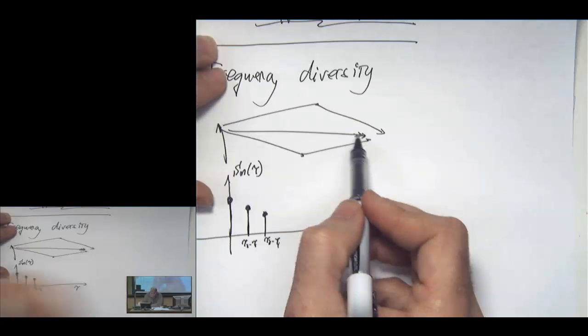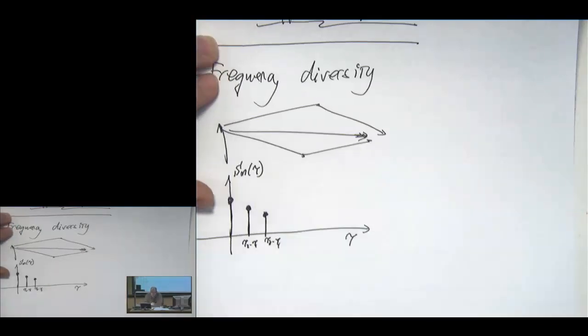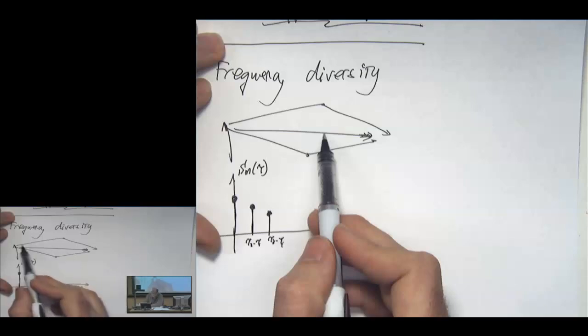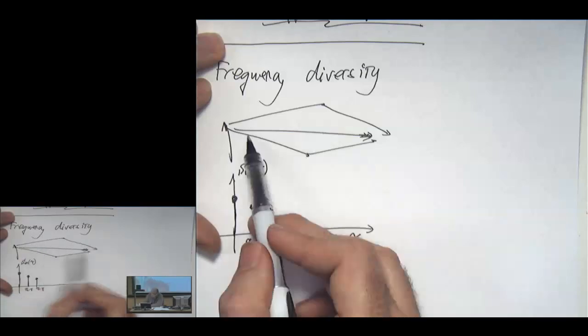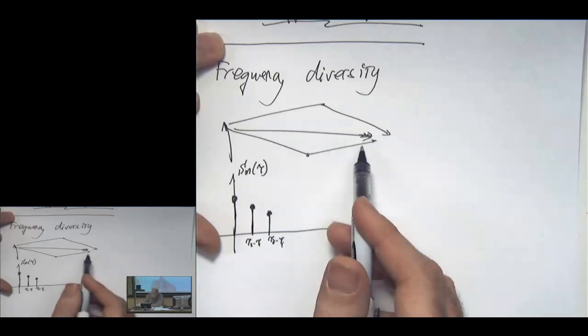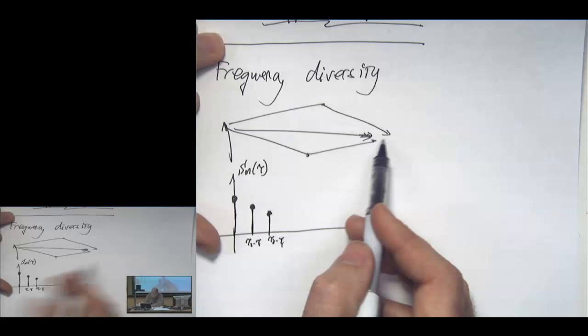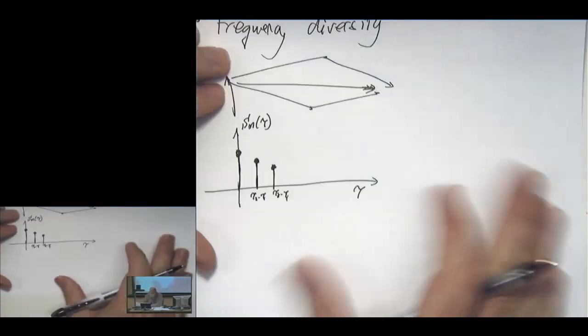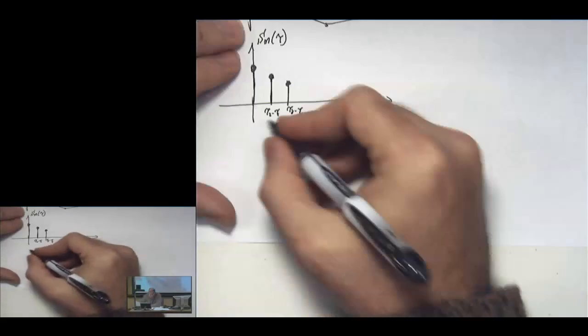And these paths themselves are actually different ways for the transmitter to get to the receiver. So intuitively, if I have a direct path and a truck comes and blocks it, there's still signal reflecting off of, say, a building here and a building here. And I can exploit this if I have a large enough bandwidth, because otherwise these are all adding up together with slightly different phase and amplitude, so they're just going to create a different fade. But if they're coming at different points in time, potentially I can exploit that. Now that sounds kind of vague, but let me give you a concrete example.